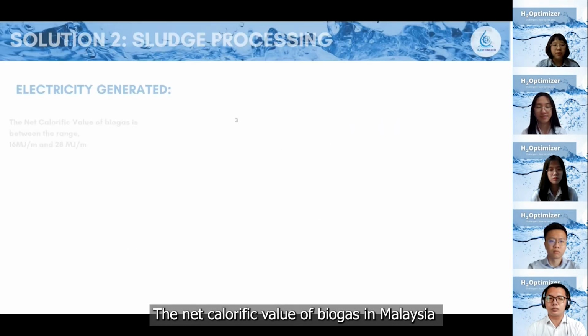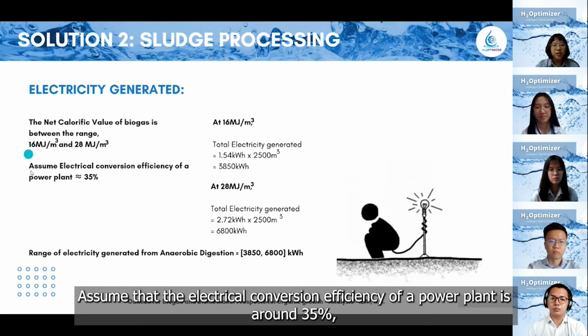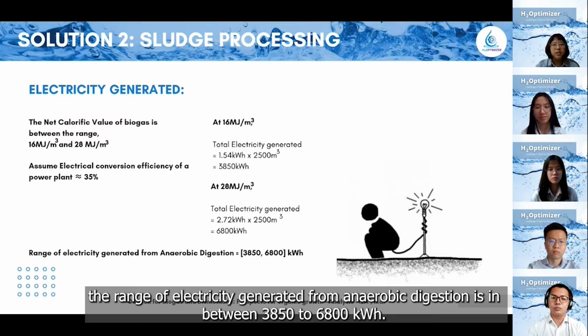The net calorific value of biogas in Malaysia is in the range of 16 to 28 megajoule per meter cube. Assume that the electrical conversion efficiency of a power plant is around 35% and the daily biogas produced is 2,500 meter cube. The range of electricity generated from anaerobic digestion is between 3,850 to 6,800 kilowatt hour.